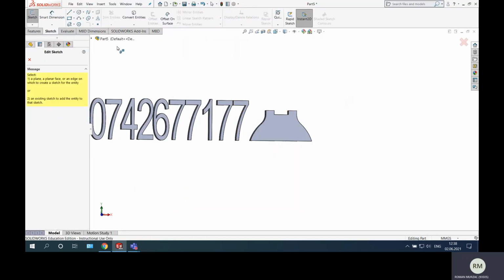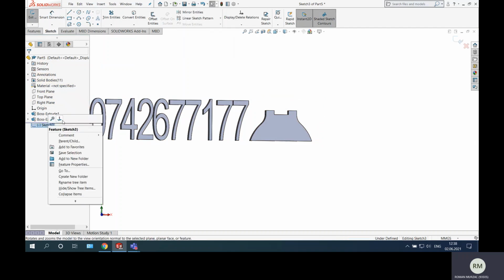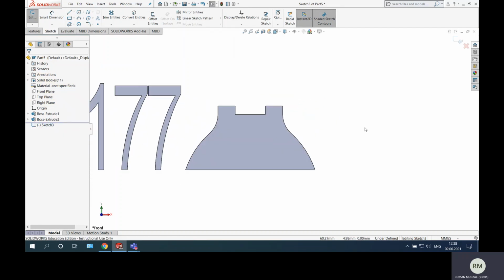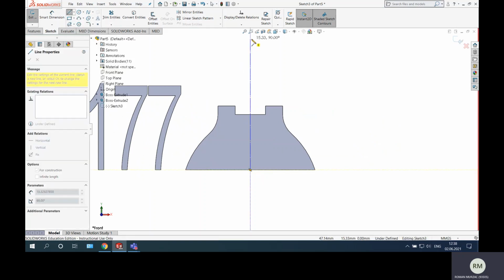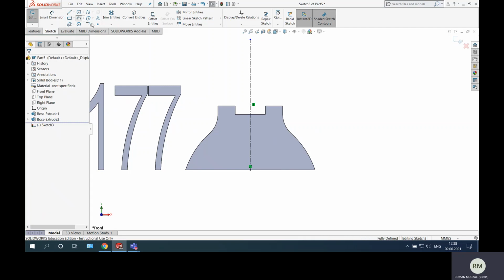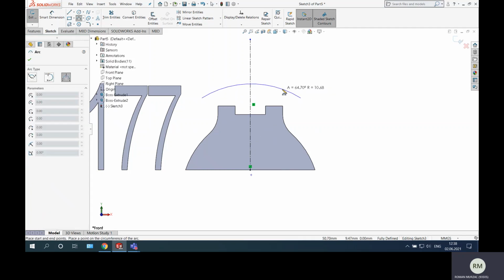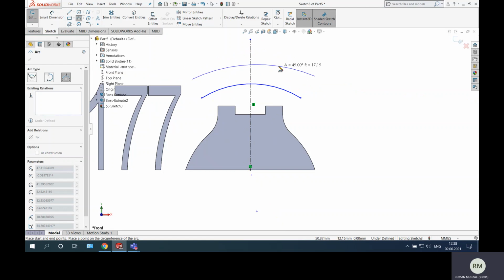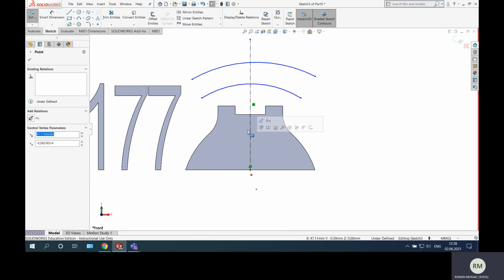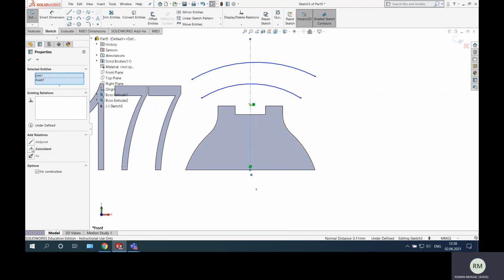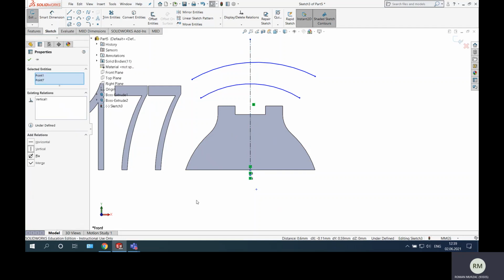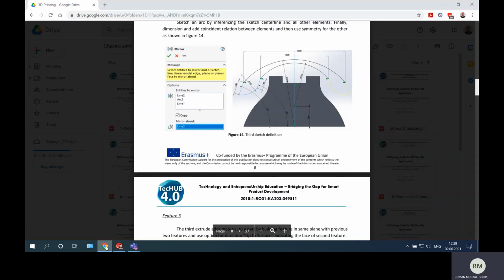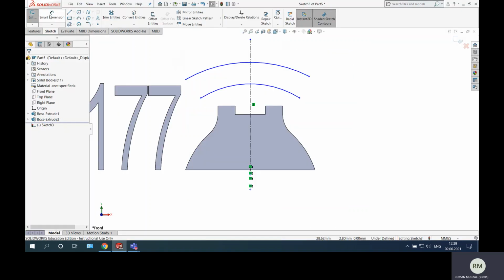Okay, so let's create another sketch on the same plane, sorry. I will start from the middle, and of course again a vertical axis, and here should be an arc like this, another arc like this. What I know about these arcs is they should be on the same vertical with the origin, and this with this also on the same vertical. Good. What I know now, I know 15 and 10 millimeters.